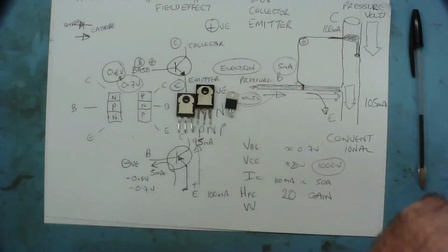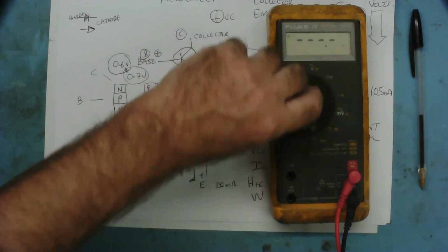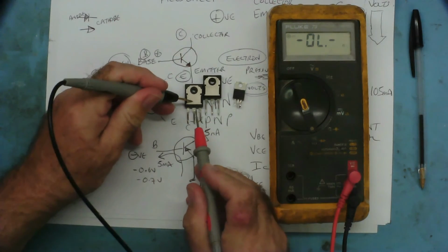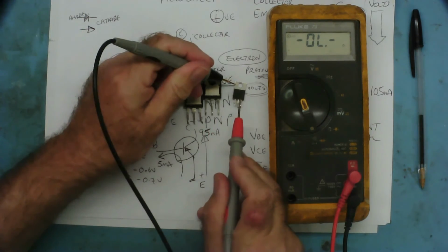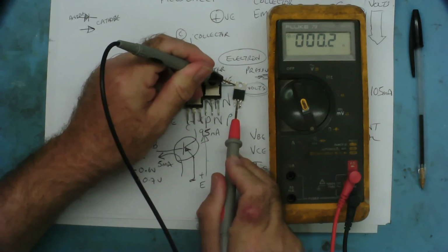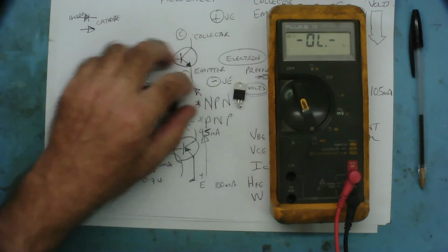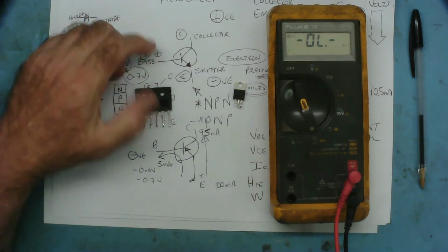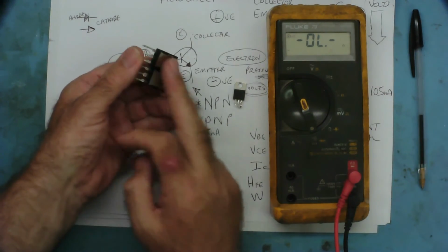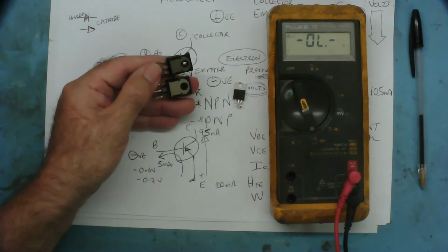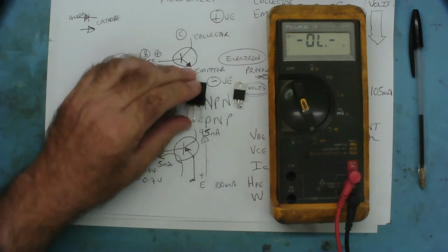Now, what you'll often find with these type of transistors is the tab is connected to one of the pins, usually the middle pin, which on these transistors is almost certainly going to be the collector. The collector is the one that has the positive voltage on. So that's why they have the insulating washer between here and the heatsink in a lot of cases, unless the heatsink itself is connected to the same voltage as the collector.